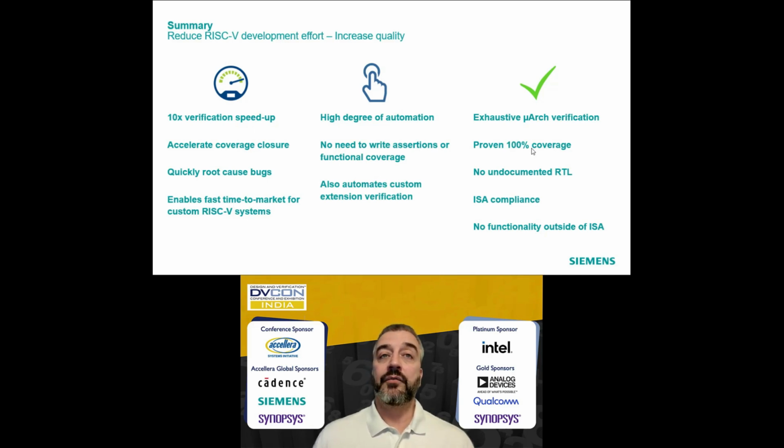If there's any functionality in your design that is not captured by an assertion, then you will get reports about missing assertions, kind of forcing you to figure out what is supposed to happen in this scenario and adding the corresponding assertions and fixing potentially also the gap in the specification. And in this way, you make sure there's really no functionality outside the ISA standard plus custom inside your core. It's only in there exactly what you want in and absolutely nothing else.